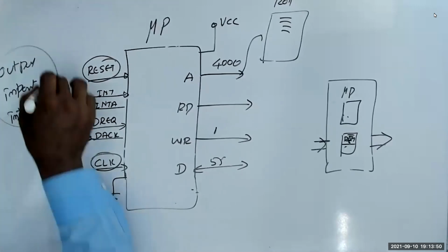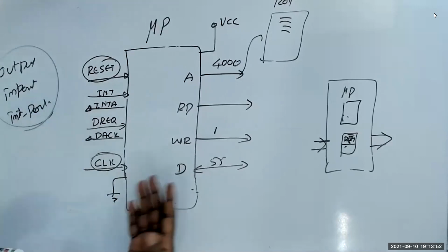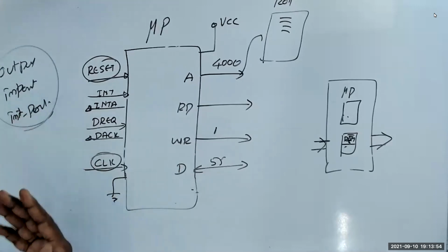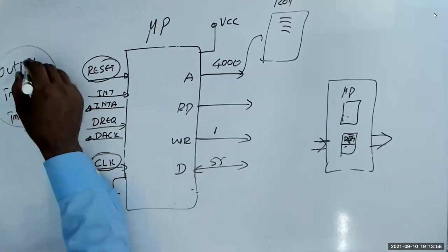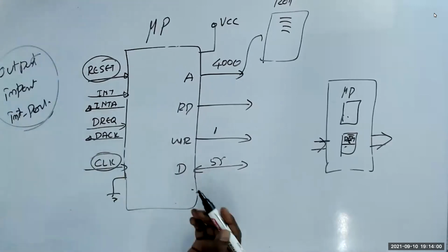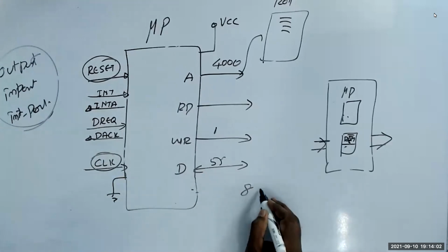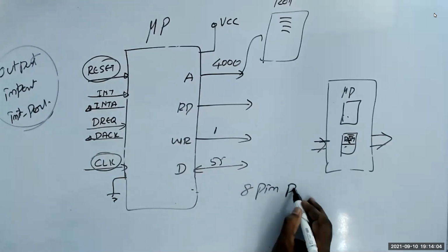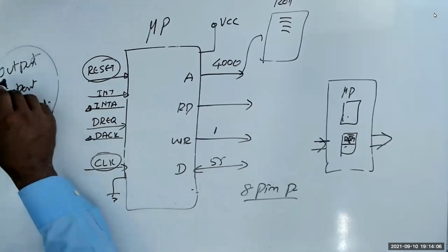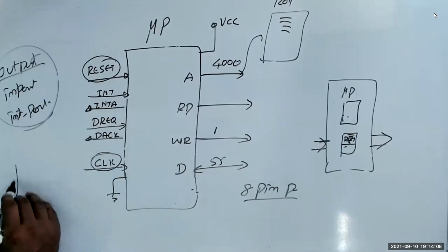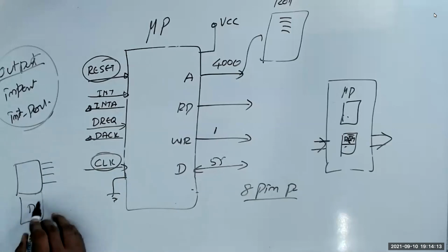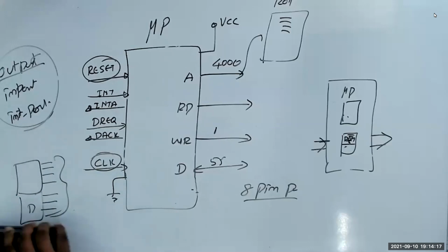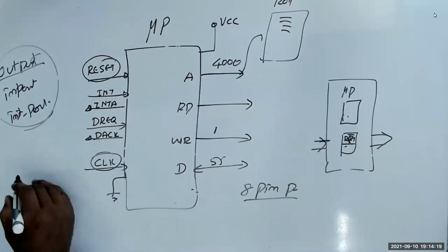This is because every microcontroller has a different address and a different way of initializing. In the case of Arduino, we didn't get an 8-pin port. So if you've seen my code, for the output I took 4 pins from port B and 4 pins from port D to make 8 pins. But if you execute the same code on an Arduino Mega, I will do that.